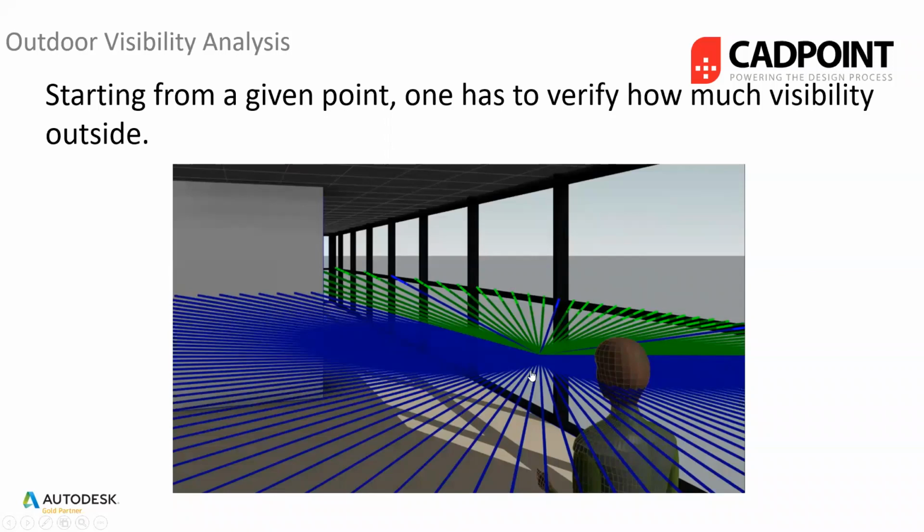You can then convert these lines into a ratio or a percentage of daylight viewing points, so that each individual chair or each individual person sitting at a desk is able to view daylight from their particular rooms as well.